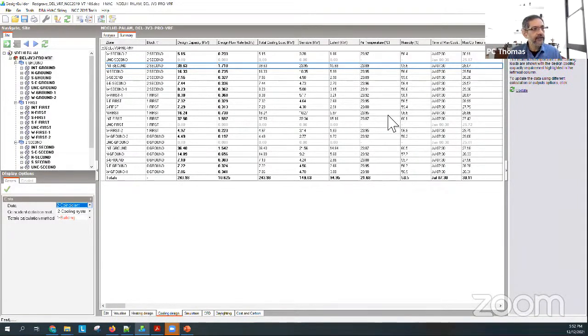You can see that what it's saying is that in July, as soon as you start the air conditioning system, that is the time the system is going to require the most capacity, even though individual zones may peak at different times. There's a concept here which you need to try and understand, but once you understand it, it's fine, because in HVAC terms they call it diversity.